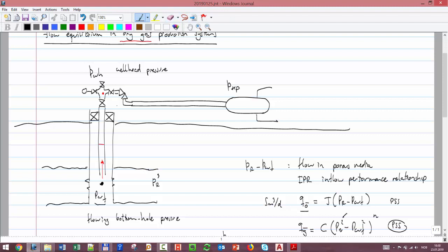Okay, and just a short comment. At the well, we have a collection of valves that are basically what we call the tree of the well. And we have some valves that are for, anybody knows what these valves are? The lower one, master valve, that's the one I use if I want to close the well for some time, completely. Then I have the two wing valves on the side. One of them you produce, the other one usually I have a pressure sensor, and then I have the one at the top, which is to make intervention, the swab valve. So these valves are not typically used in normal operations. They are on and off.